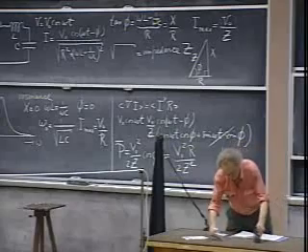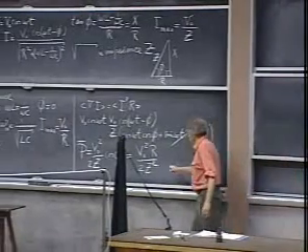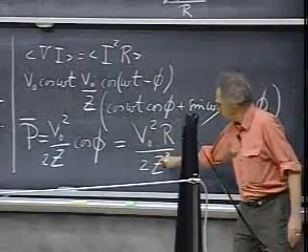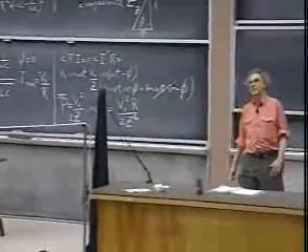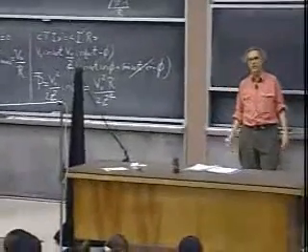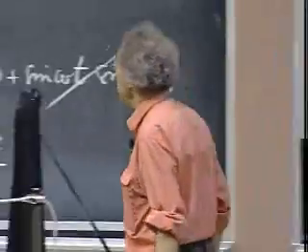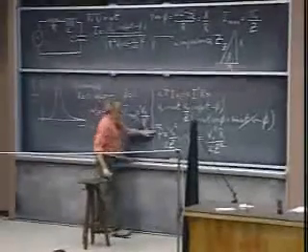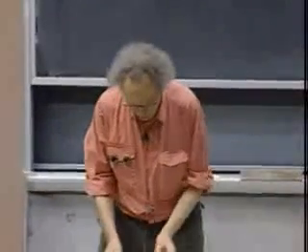So now we can look at resonance. It's always a very special situation. When we are at resonance, Z equals R. So you replace this capital Z by R, and then you find V0 squared divided by 2R. That's utterly trivial. You could have predicted that. It's really Ohm's law staring you in the face. There is no self-inductance and there is no capacitor at resonance, so you might as well have treated it as a simple system only with R, and you find immediately that answer. At any other frequency than omega 0, Z would always be larger than R. You see that immediately here, and so that means that the average power would always be lower. So it's only at resonance that you generate the highest power possible.